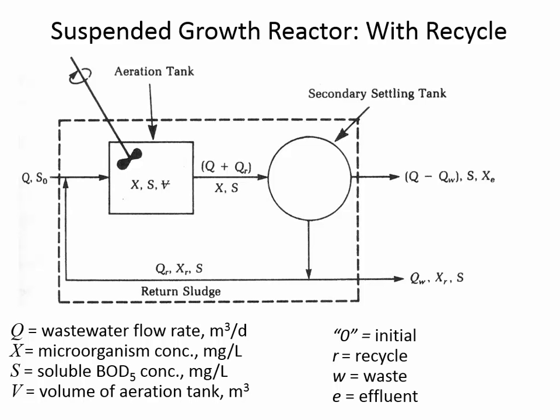How come S naught is different from S in the aeration basin? How is that possible, that the inflow concentration isn't the same as the concentration inside the reactor? Yes? As soon as it enters, it's mixed and the bacteria are eating what's in there. So it's not that all of the BOD is instantly consumed, but it's instantly diluted because it's a well-mixed reactor.